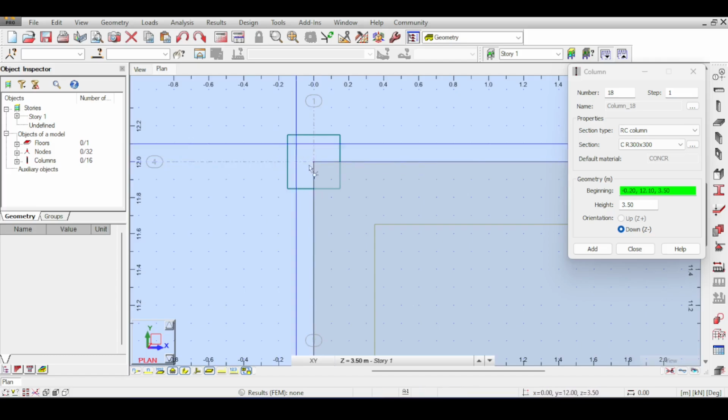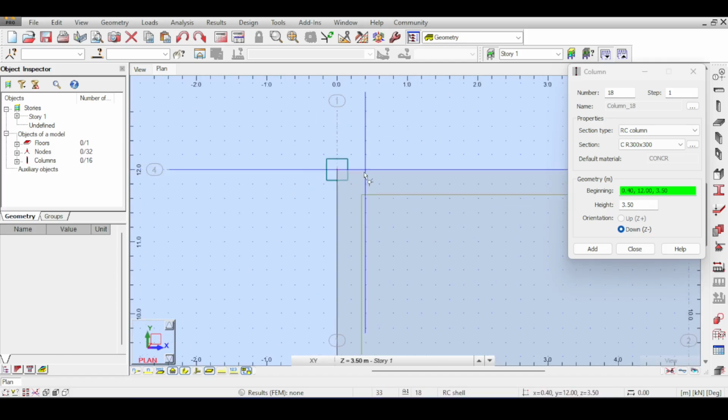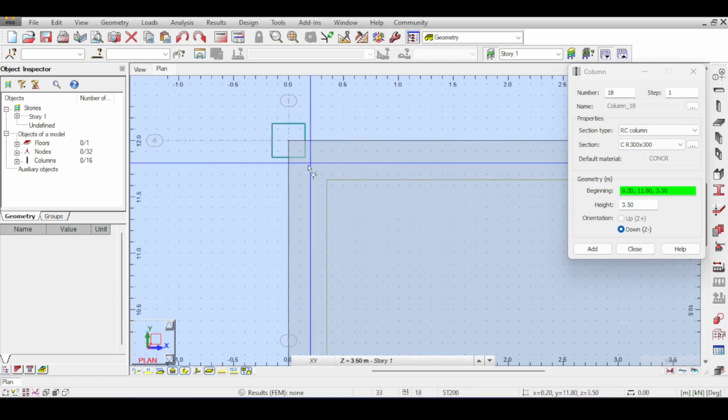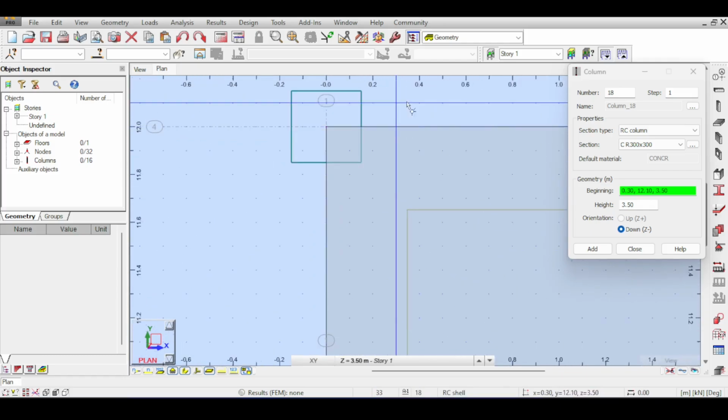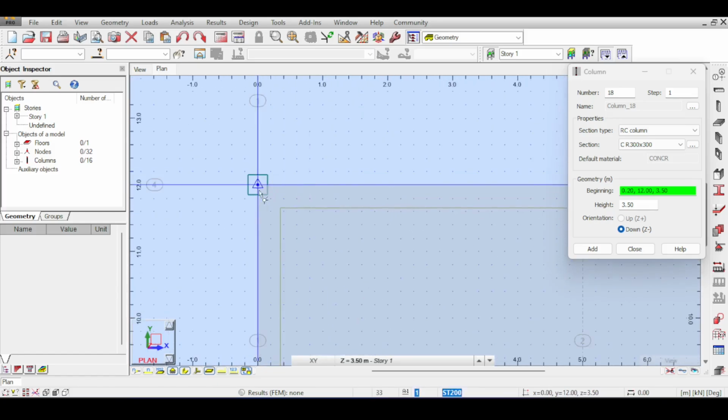Now this column seems to be odd because it's not really carrying the entire plate, and that is unfortunately true, but this is a limitation in the finite element method, as you know that the edge point must connect to the center of the column, although in reality it's actually a little bit inside. Hypothetically, you could just draw the column here, for example. Let me show you.